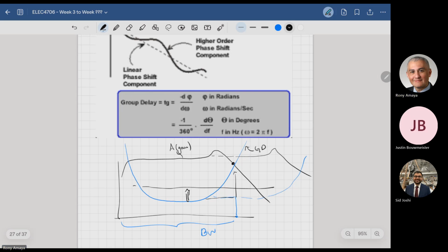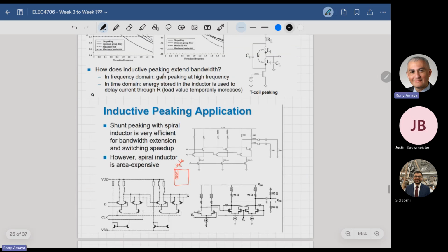Group delay, which again affects intersymbol interference, closes the eye. Then you have noise, which also limits how well you can detect the signal. One is jitter, and the other affects the thickness of the eye on the bottom and top of it, which closes it as well. And then you have group delay variations, you have gain peaking, and all sorts of stuff happening at the same time. Is that clear?